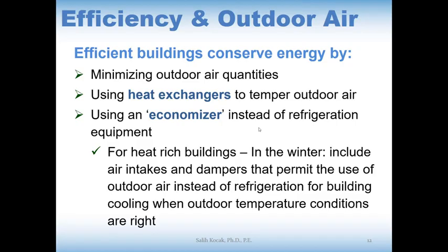You can think of it this way: when outdoor air is brought into a building, it displaces the conditioned air. So outdoor air is coming into the building and displacing the conditioned air inside. So efficient buildings include heat exchangers to temper outdoor air.